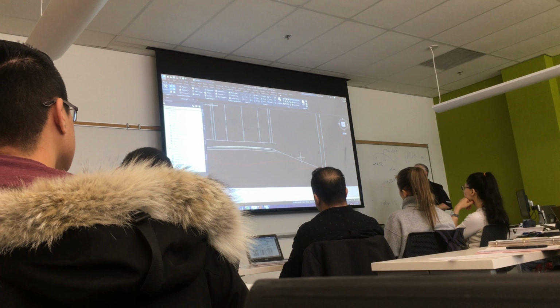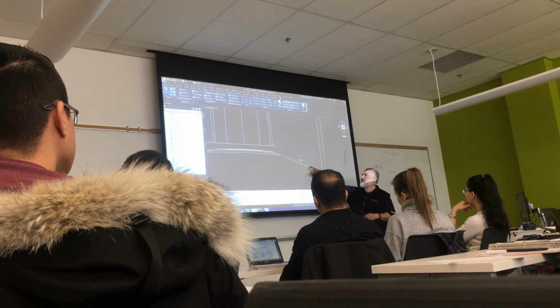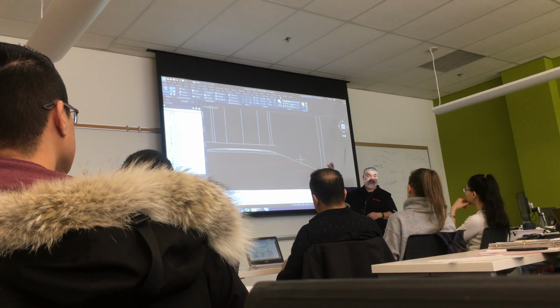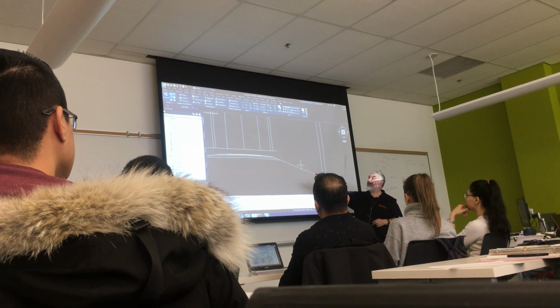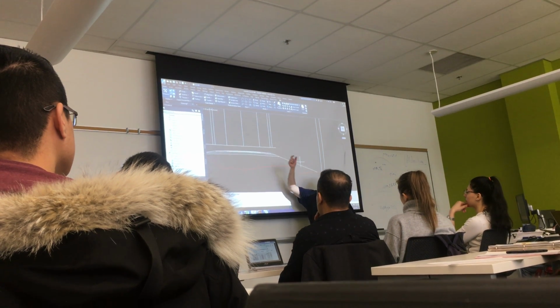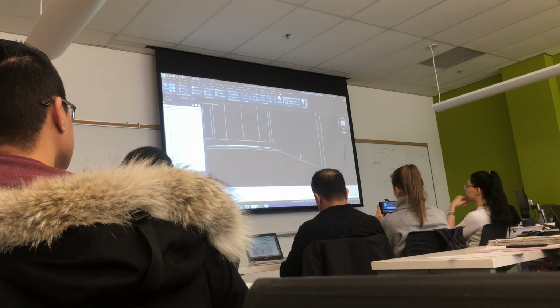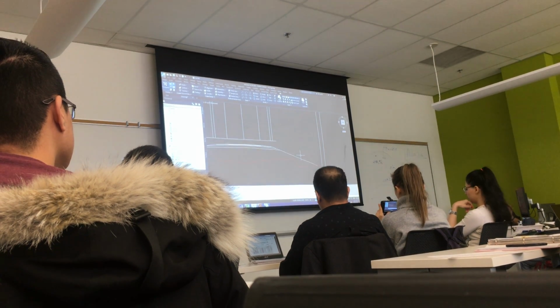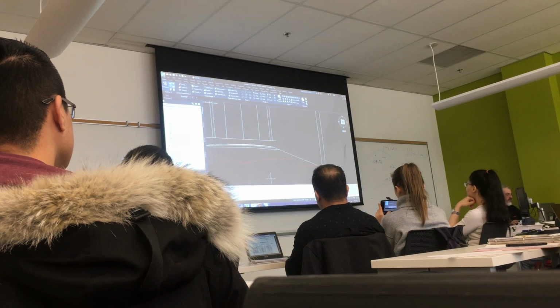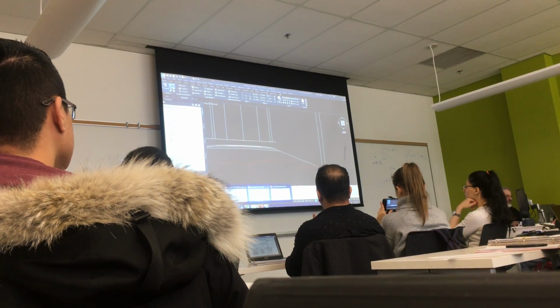Okay. I'm not going to do it now, but remember this is not 6:1, so we need to analyze this. If I need a guide rail, I have to make this ½ meter wider. I'd have to extend the plane of the shoulder. So instead of just a rounding of whatever, I need an extra ½ meter. What am I talking about? Let's go back to the cross section.